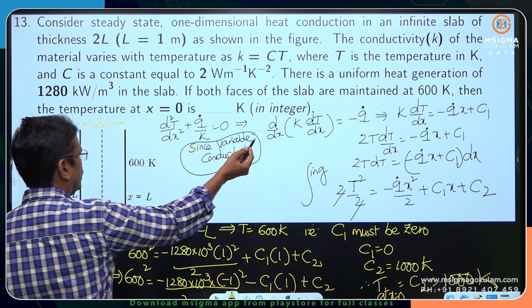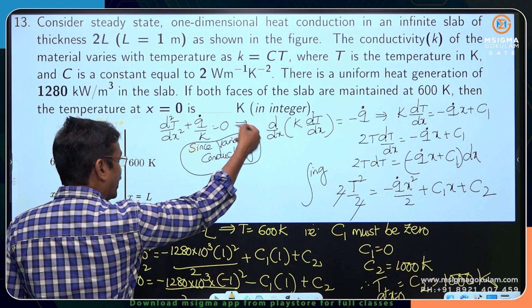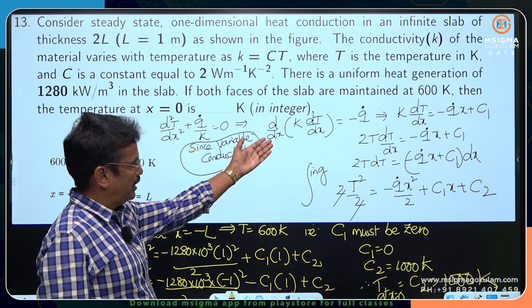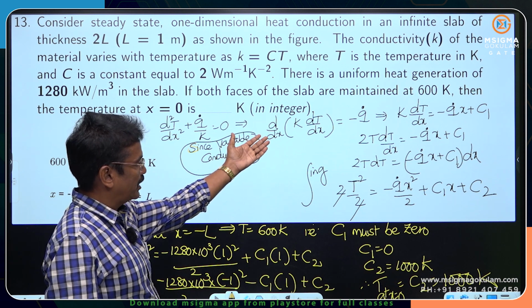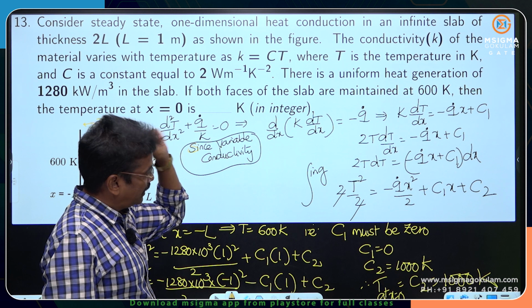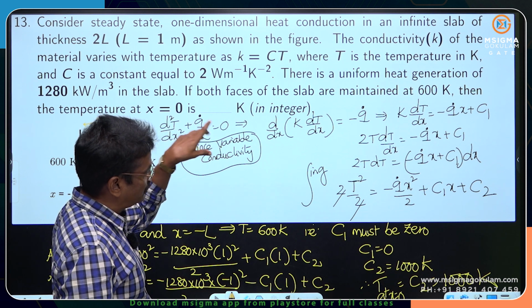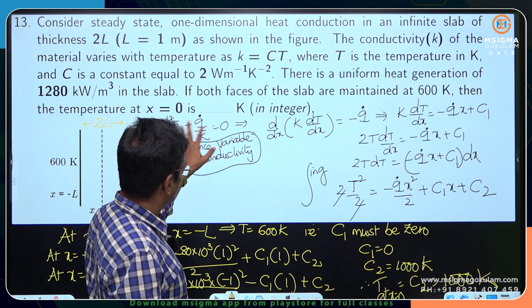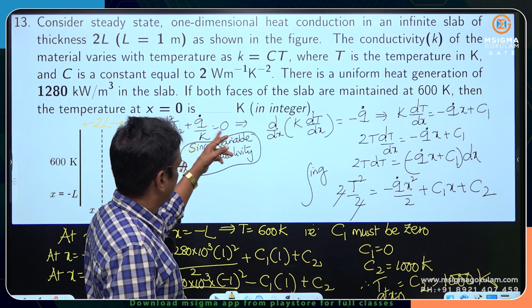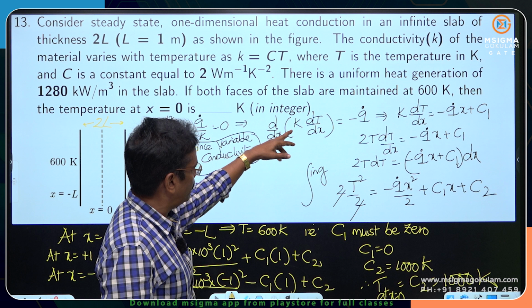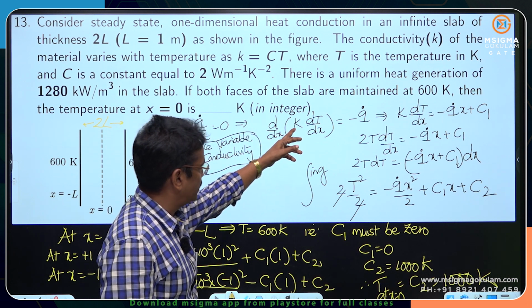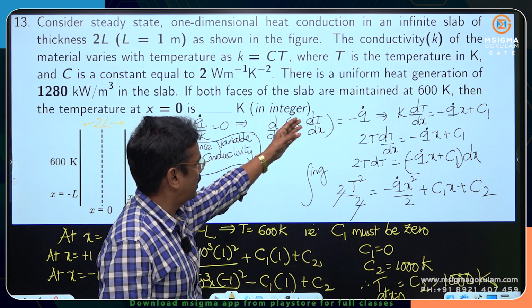Going to the fundamentals of the equation which were derived in the earlier case, look at the basic derivation of the generalized heat conduction equation. In that derivation K was assumed constant, so it was taken out to obtain this. If K was not taken out, because K is a function of temperature or a function of X, then this is the result.